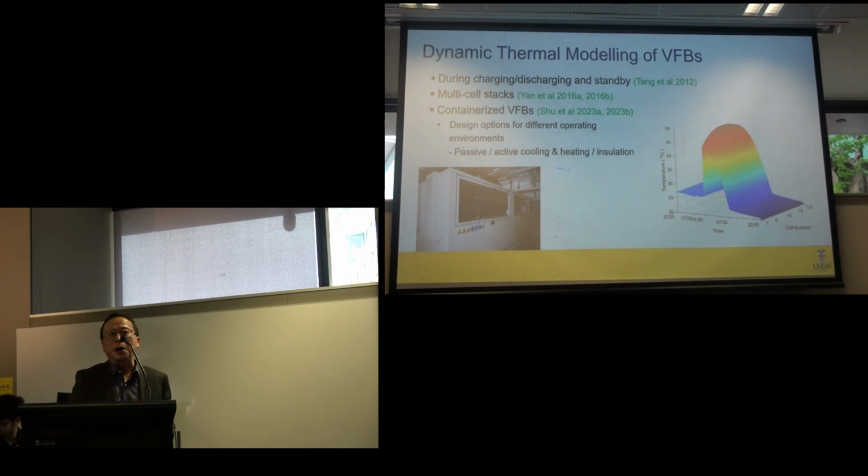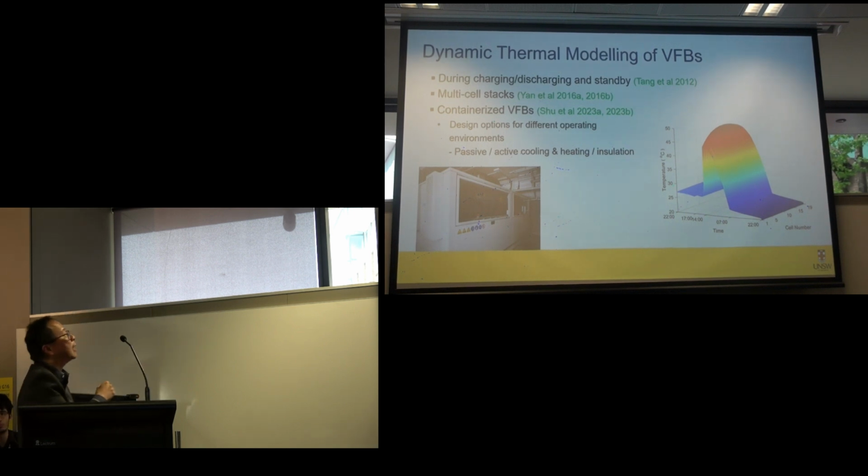We work on the thermal modeling for the batteries, particularly during charging, discharging, and also standby. And I'm not sure whether Dr. Itao is here, but we worked on the multi-cell stacks, the heat generation in the cells, and also the temperature profile at different cells in a stack. This diagram shows the different cells in a stack and the temperature distribution during self-discharging and standby.